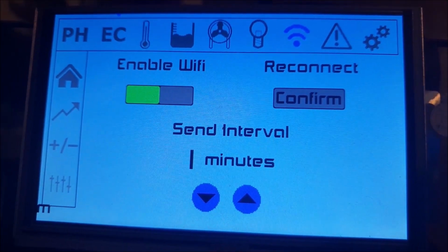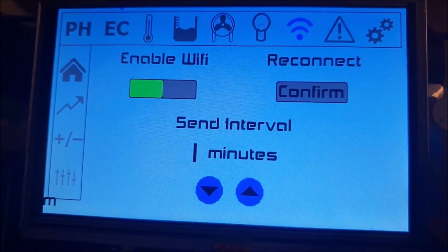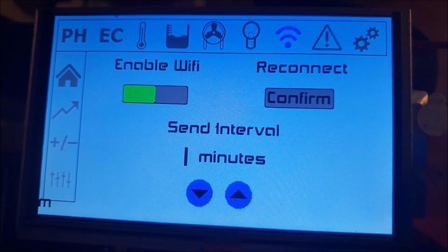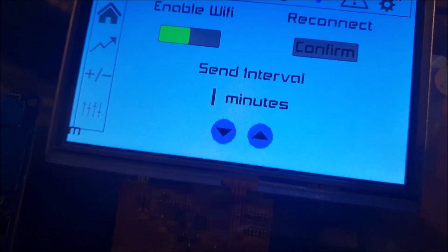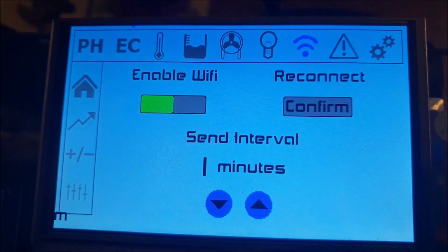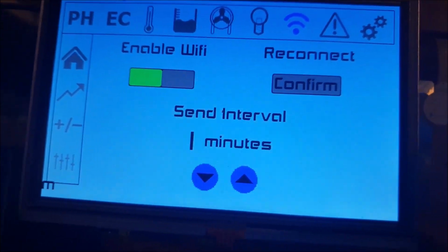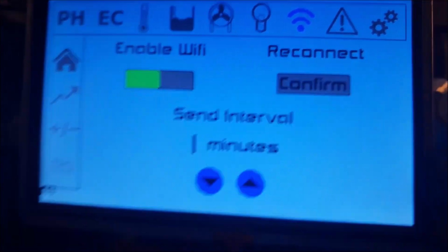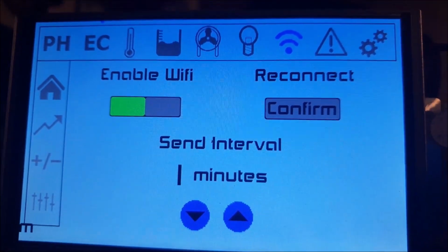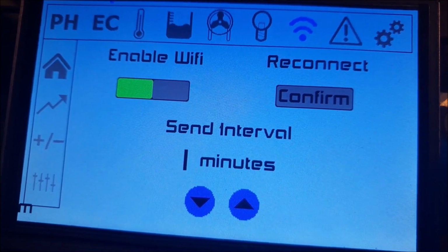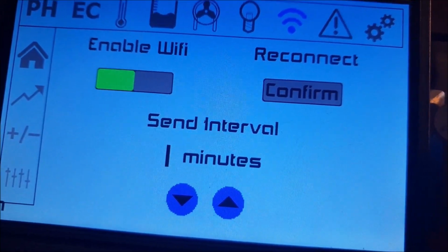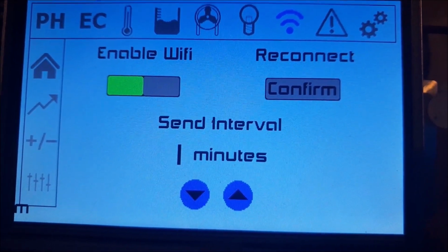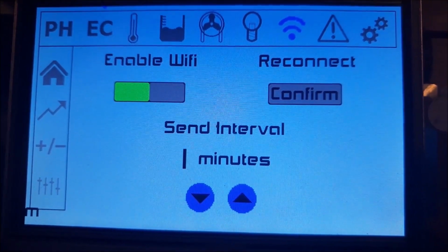Then however many days or hours or minutes later it took to get back to that original value, it can then go into the EEPROM and say, blah blah blah, 5 times something equals block 10. Is there a value in block 10? Oh yes, there was. Well, what did you equal? When I did the dosing, I was 5 and it went up to 6 at the value of 5. To which it can then say, okay, if I want to get to a value of 6 or 7, let's say, I need to double my dosing.